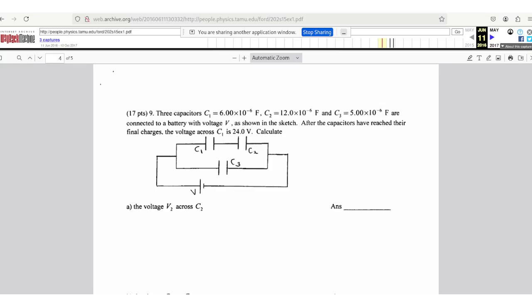And then the other loop law is grab this guy here going this way. So then we have V from the battery minus the capacitor V3 is equal to 0 volts, which means that V of the battery is equal to V3, which we already knew to be 36 volts.